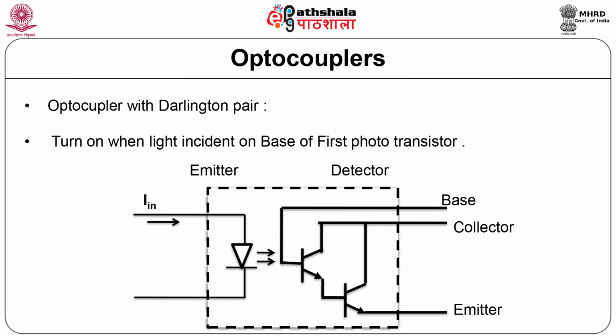This is required to serve as a photodetector output section. In the circuit, the output current IC of a single bipolar phototransistor or the photo-Darlington will develop an output voltage VL across the load resistance RL. This voltage is the product of output current IC and the load resistance RL.